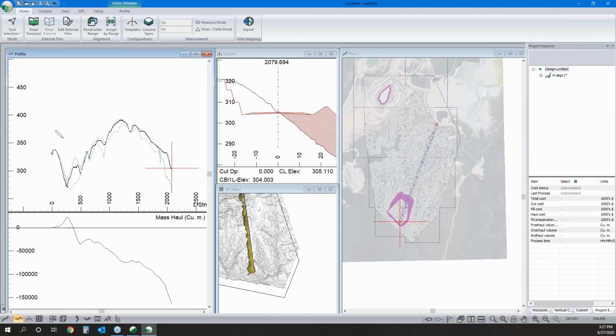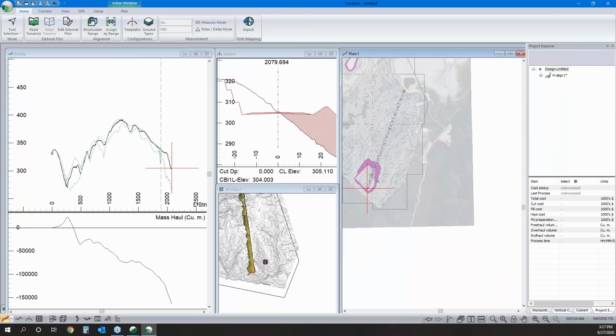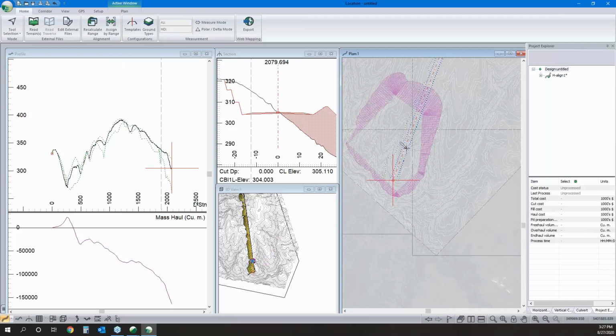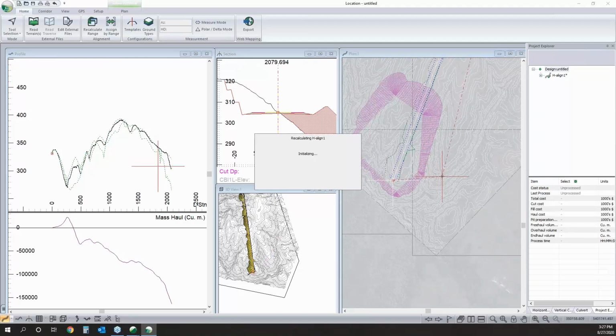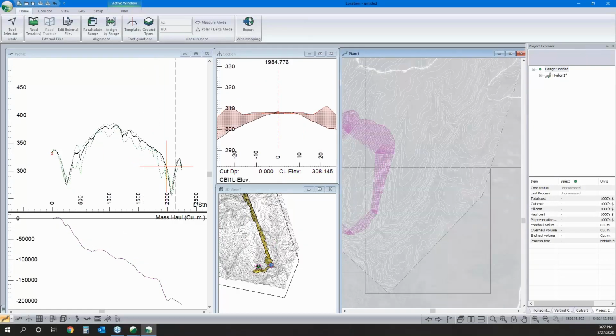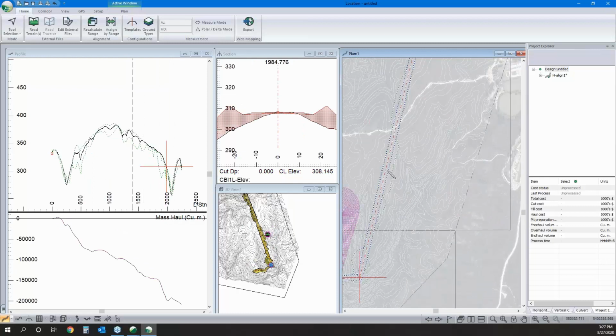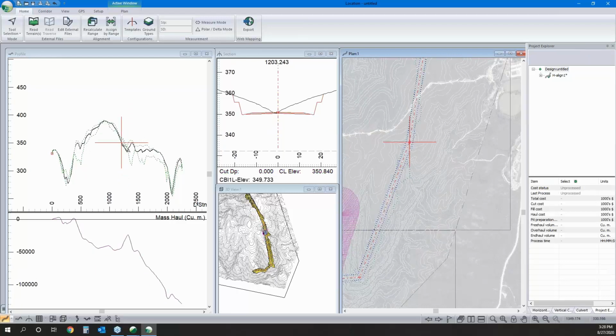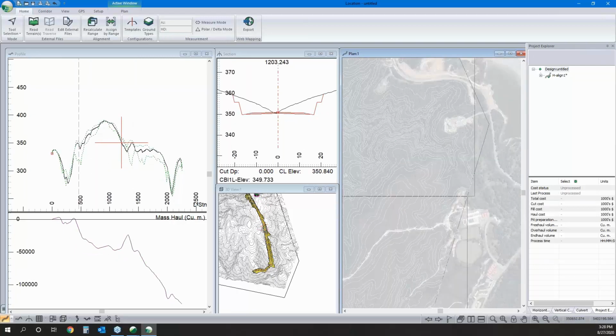We can see the profiles updated now. Since it's not a single point, we can see a draped line showing what's where. And I'm going to start by making this actually resemble something. So we could click through doing both views at once. I'm just going to click in something that I think is close to reasonable for a start alignment in my horizontal, and then we'll refine it.